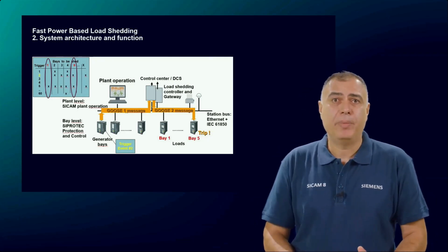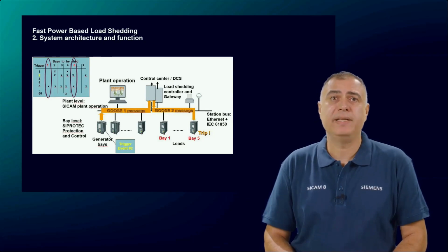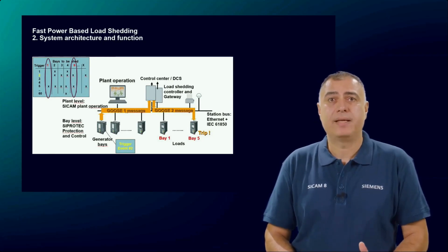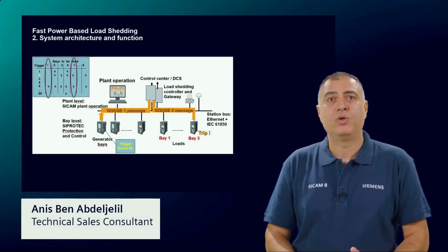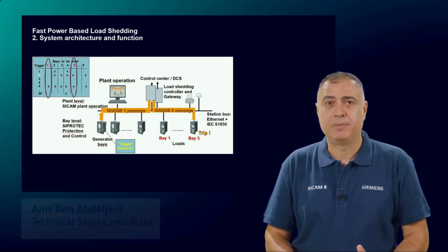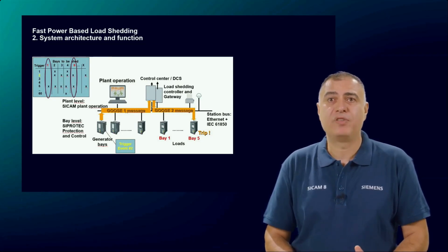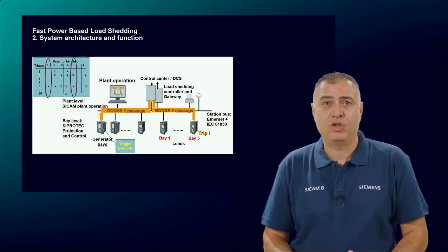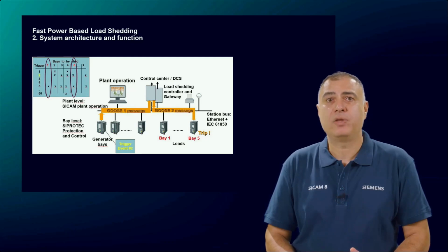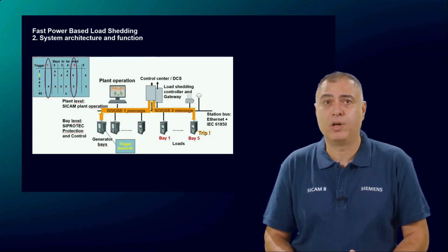Using the received information from the contingency and the load protection relays, the singular or redundant controller is updated. With this actual information, the controller pre-calculates the so-called trip matrix. On the left side on top, you can see an example of such a table. To enable a very fast reaction, the trip matrix is stored at the IEC 61850 interface of the controller.